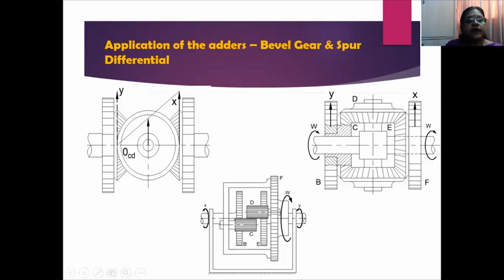Now, if you draw a triangle here, if this is the X displacement, then the center arm position will be X by 2, because if this entire thing is capital D, then this will be half of the diameter, thereby this value being X by 2. So the ratio of these gears will be, if this is X, then the motion on this will be X by 2.